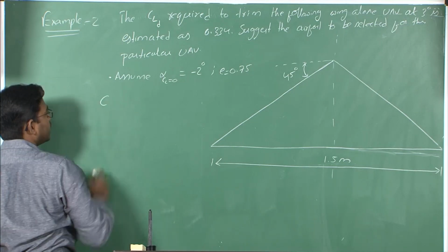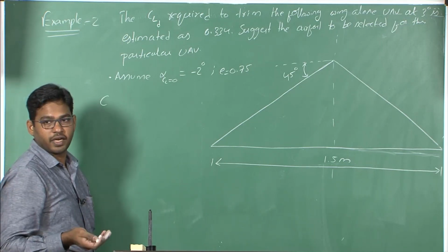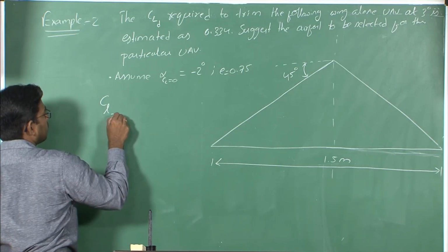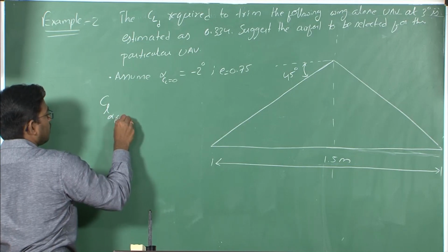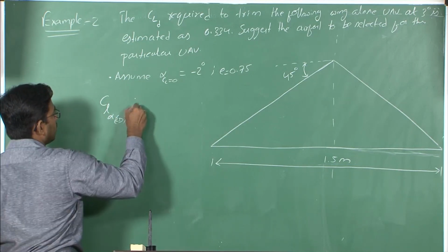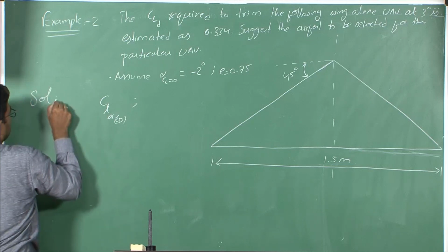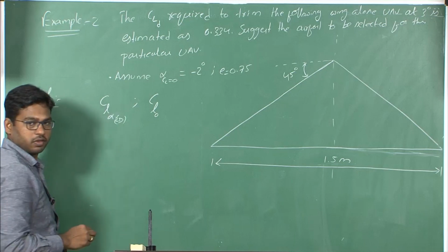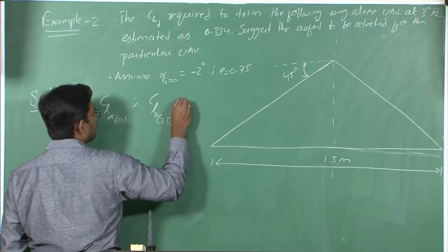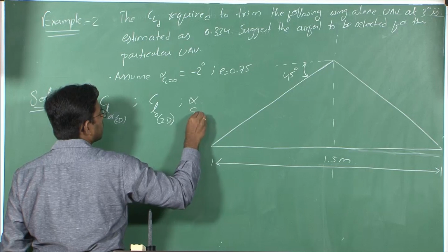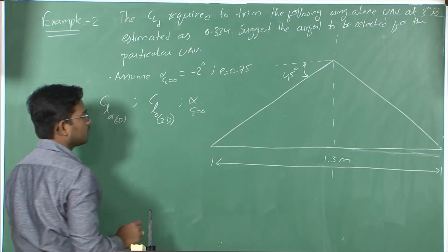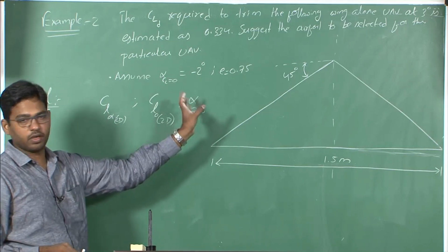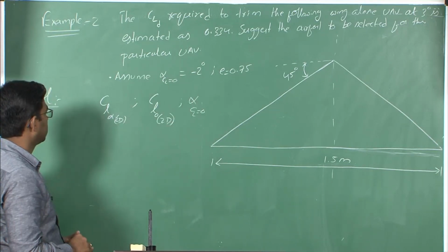In terms of lift and drag characteristics, say lift characteristics here, we need to give what CL alpha 2D of the aerofoil should be, say CL naught 2D of the aerofoil, and say the alpha at which CL is equal to 0. This is already given, because for wing as well as airfoil it will remain the same here, that is the assumption that we have.